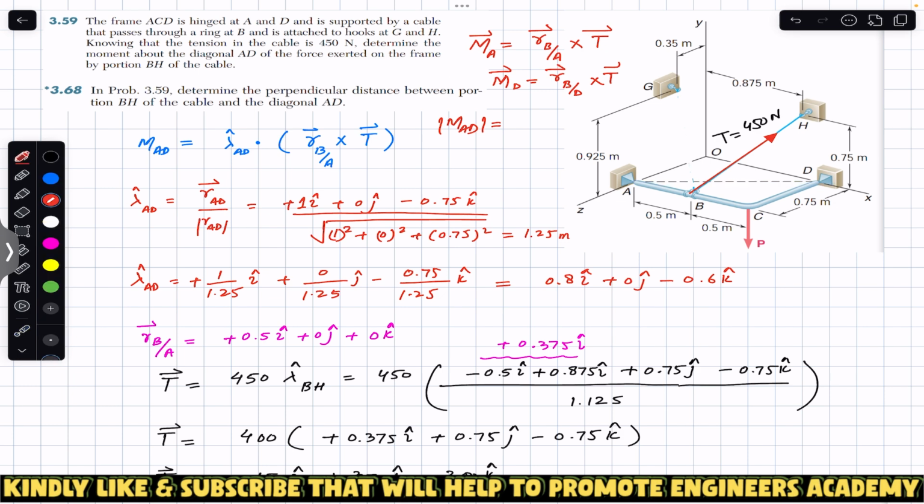So we can write that the magnitude of the moment about that diagonal AD will be equal to MA vector dot product with the unit vector from A to D. Or we can say that this magnitude will be equal to the moment about D dot product with the unit vector along AD. So this is the first method you guys can do to find the moment of this particular tension about this line AD.